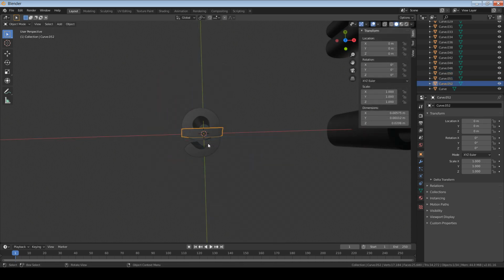Last but not least is the underscore. Once again, move this to 0, 0, 0, and this time we're going to be moving it down the Y axis. For this font, I found that I like to move its default origin point down the Y axis by about 4 times its thickness. So I'm going to go ahead and change its Y coordinates to negative 0.00448. Of course, this will change depending on the font.